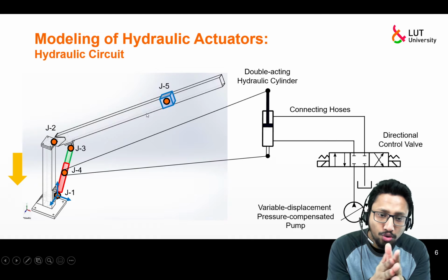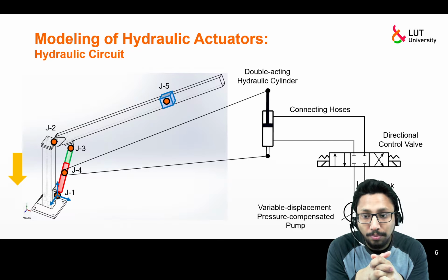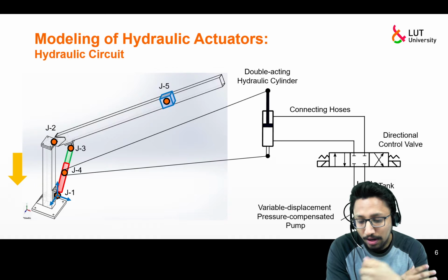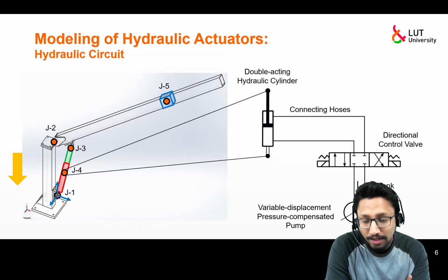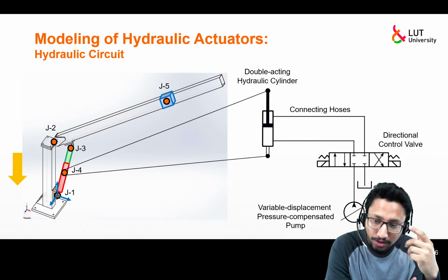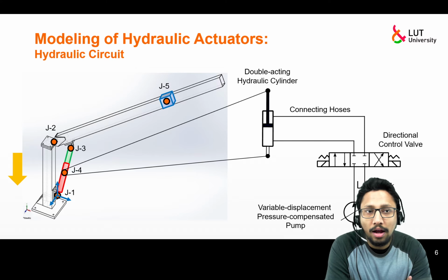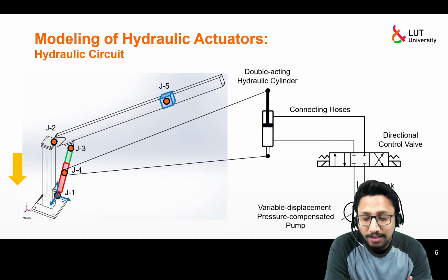What will these joints be? You need to figure that out because it is your job. One thing that we can tell you is that the overall degree of freedom of the system would be 1, and you need to check very carefully that you do not have any redundant constraints in the system.